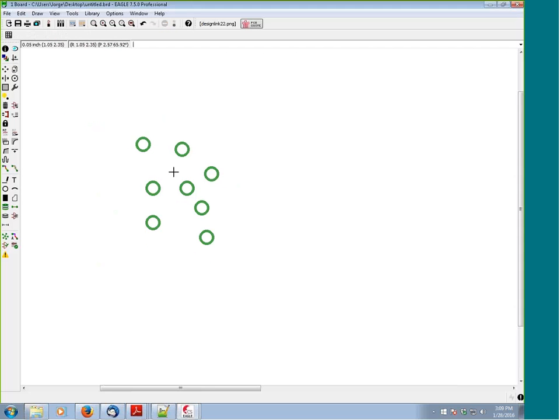Oh, you can't do that with the vias on their own. You can do it with pads in the library, but you can't do that with the vias here. I apologize, that was a mistake on my part. But you can do it with components, like LEDs and stuff like that, as long as it's a component. Vias don't count because they're not considered components in Eagle's parlance. If it were a pad, it would work, but here with the vias, it does not. Okay.